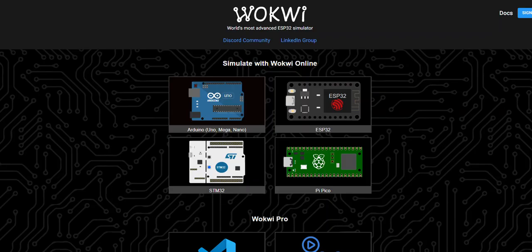So we talked about I2C and SPI, and they're used to communicate with other sensors or devices on the same board. For wireless communication, Wi-Fi modules allow the Arduino to connect to a network and send HTTP requests or push data to MQTT brokers. Bluetooth and Zigbee are also commonly used in wearable and low-power applications.